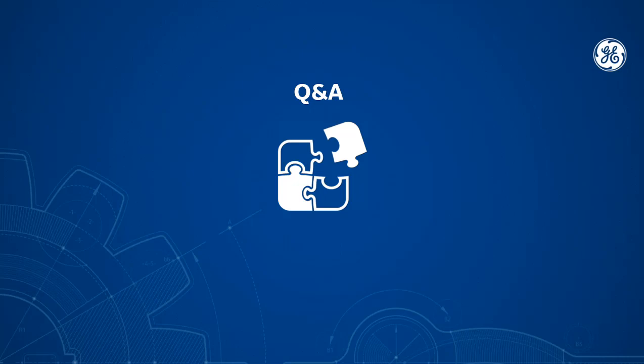Okay. Thank you. The next one is, how do we select whether to use externally fused versus internally fused bank? So if it's completely open-ended, it's all dependent on cost and the size of that capacitor bank. If it's a smaller bank size, if it's at 34.5, I'll generally choose an externally fused.